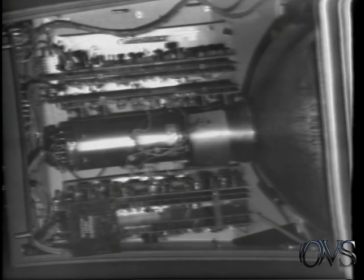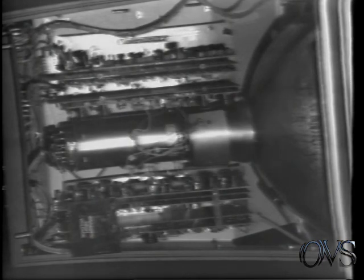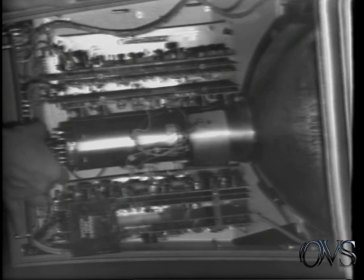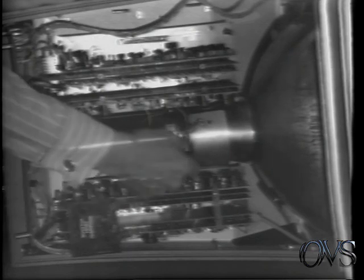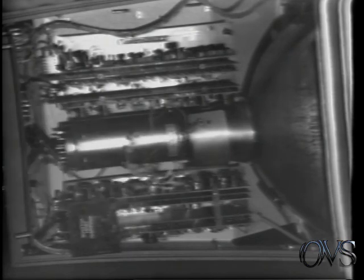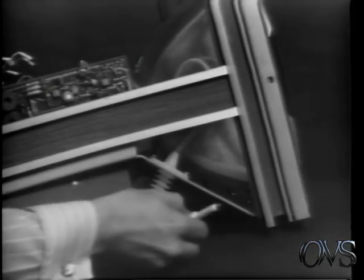Our final topic is CRT removal. We'll use a model 1311A for demonstration. However, the procedure is the same for both instruments. First, remove the CRT base socket and loosen the clamp. Next, disconnect the neck pins. Disconnect the post accelerator lead and immediately discharge it to ground.